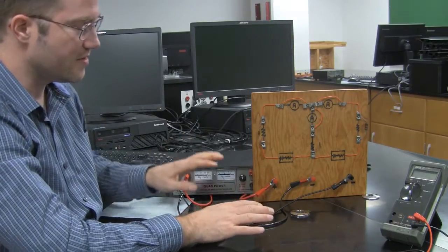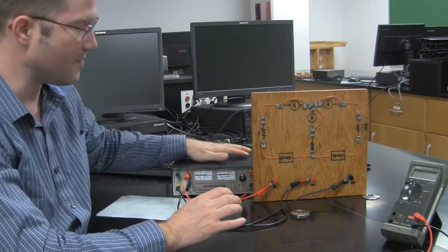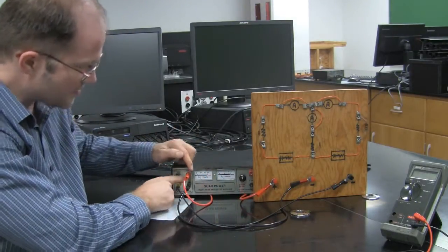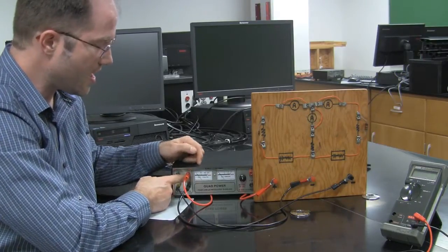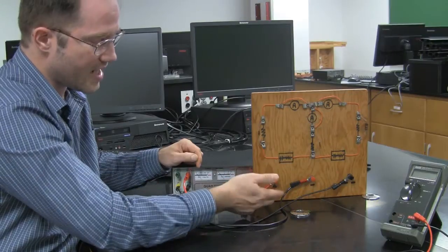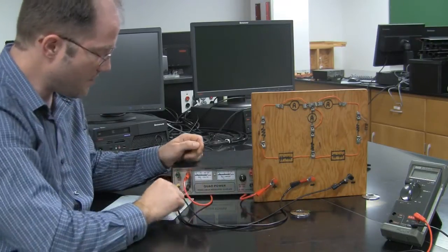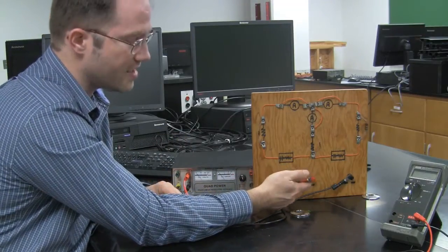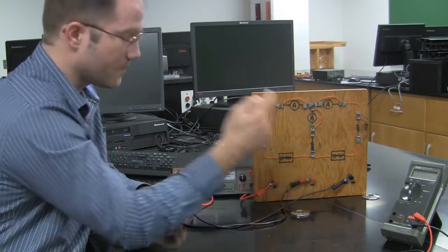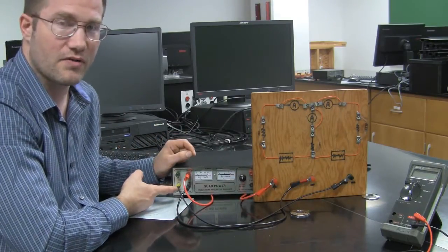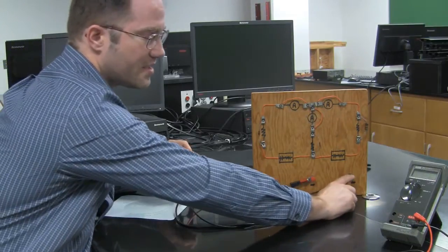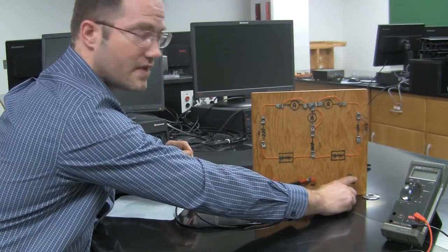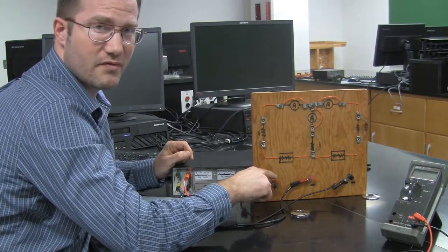Basically, to attach this to something in real life, I've got my power supply here, and I'm going to energize this board. I've got a 12 volt range that I'll attach to this far left side. It has a positive sign underneath it. There is a common, COM, which means ground, that I'll attach to the middle here. It says negative, but this is really ground here in the center. And then I have negative 5 volts coming from this quad power supply that I attach over here on the far side where it has a double negative. So this is common, more negative, it's negative 5 volts, and then more positive, positive 12 volts.